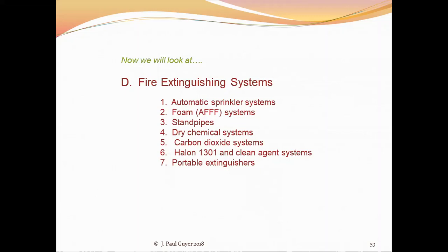So it puts the fire out that way. The carbon dioxide systems cannot be used in locations where there are normally people present, for the simple reason that if you remove the oxygen from the atmosphere, then the people are at risk.